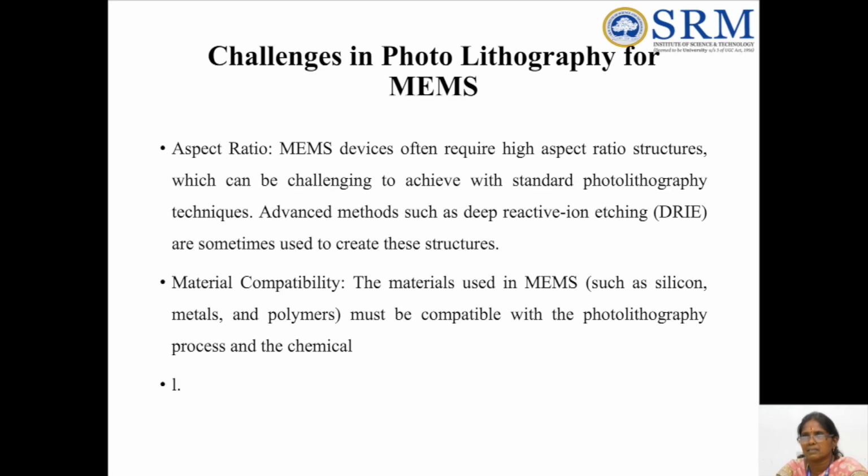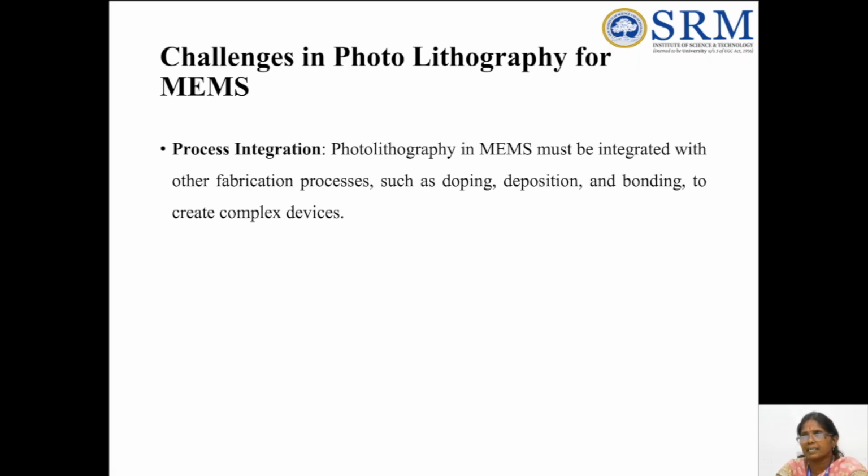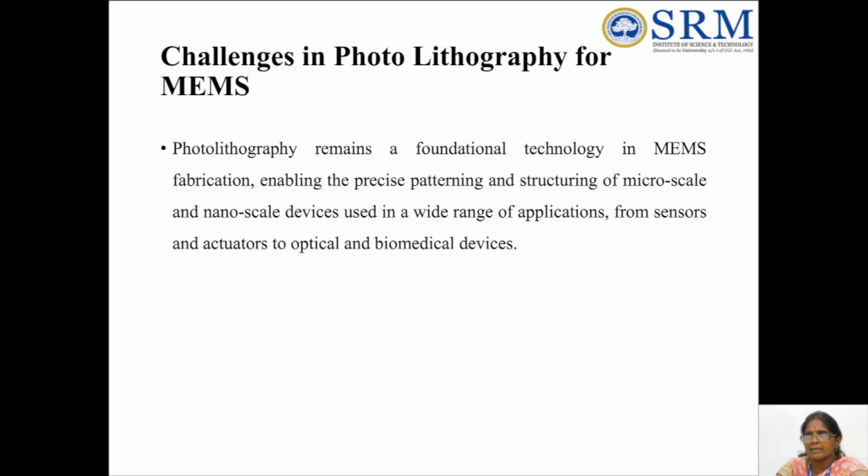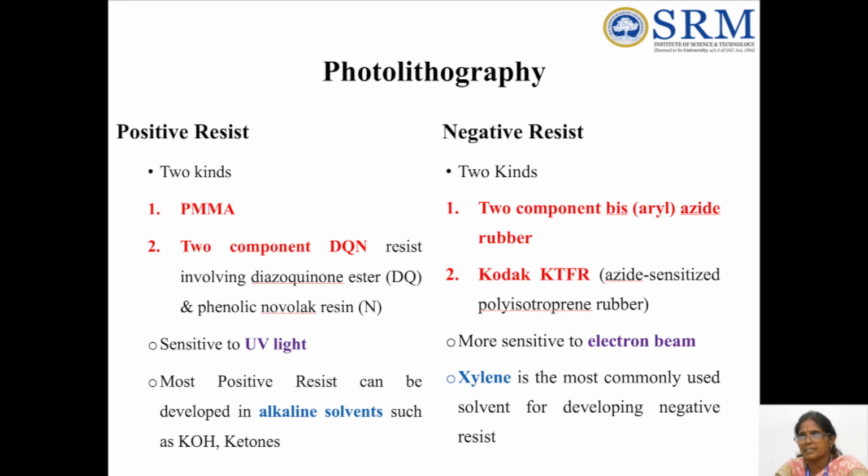Next one is process integration. Photolithography in MEMS must be integrated with other fabrication processes such as doping, deposition and bonding to create complex devices. Photolithography remains a fundamental technology in MEMS fabrication, enabling the precise patterning and structuring of micro-scale and nanoscale devices used in a wide range of applications, from sensors and actuators to optical and biomedical devices. What is the comparison between positive photoresist and negative photoresist?